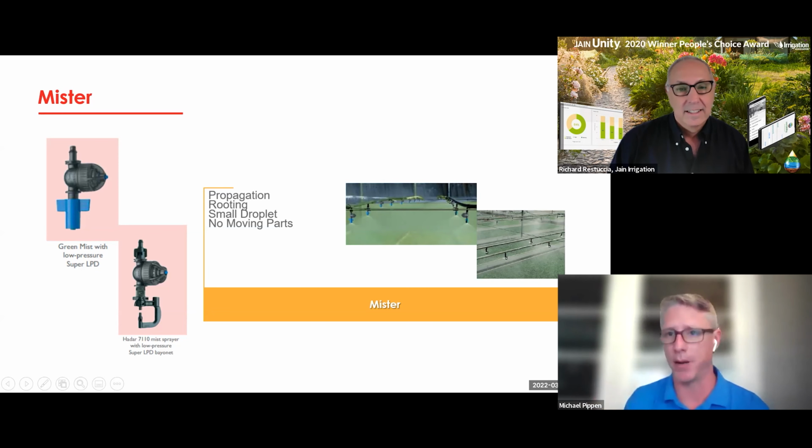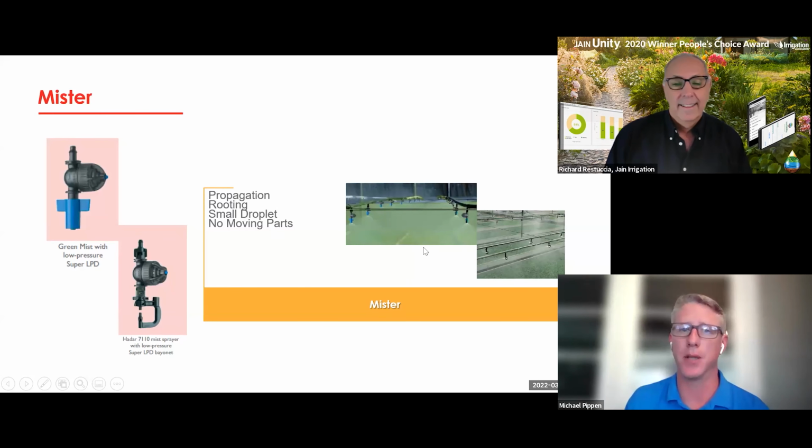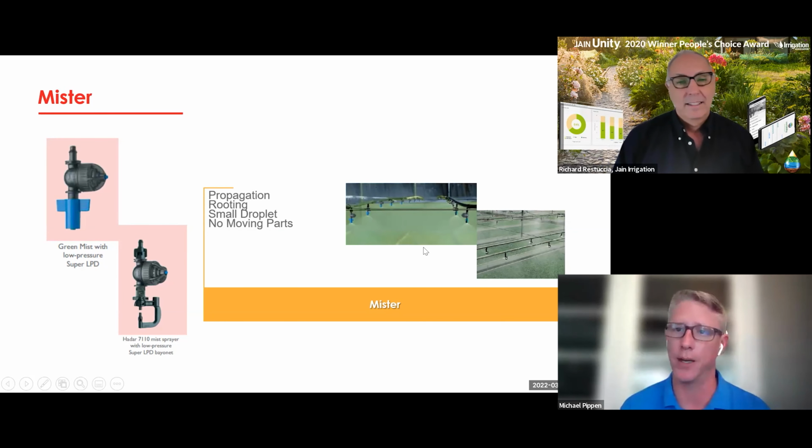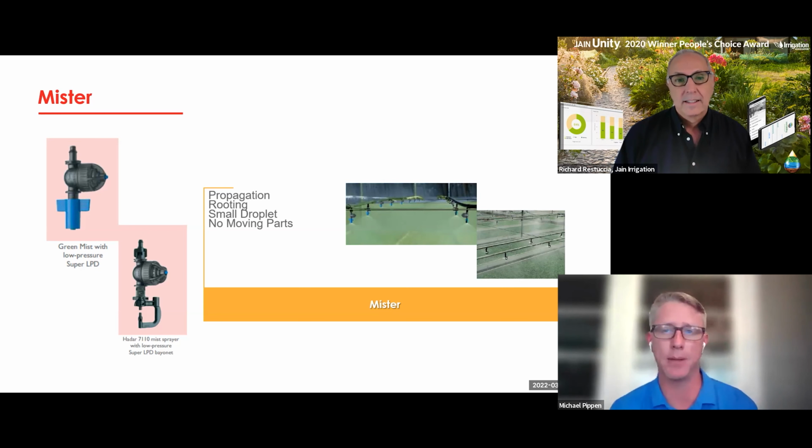And when you turn it back on, it never gets full. All you do is just leak water the whole time. So that leak prevention device is a check valve, but it's designed for a certain pressure at certain flow rates, so that it opens when we pressurize the system and closes when we turn the system off, allowing us to turn the water on in short bursts, is probably the best way to describe it.